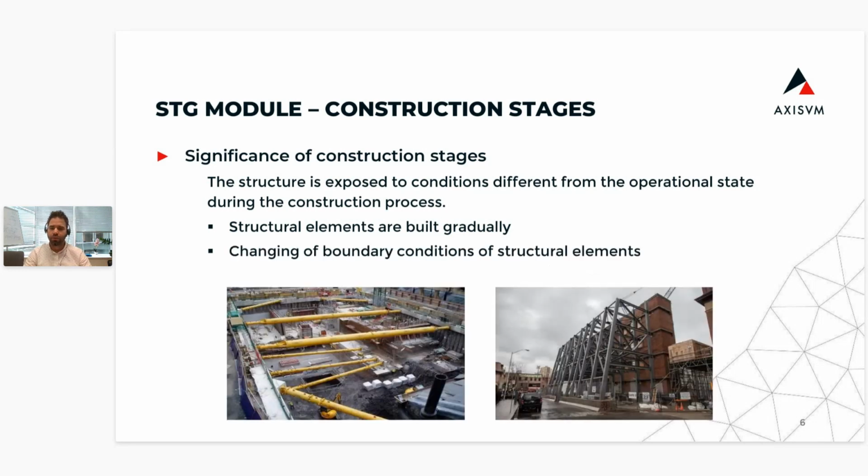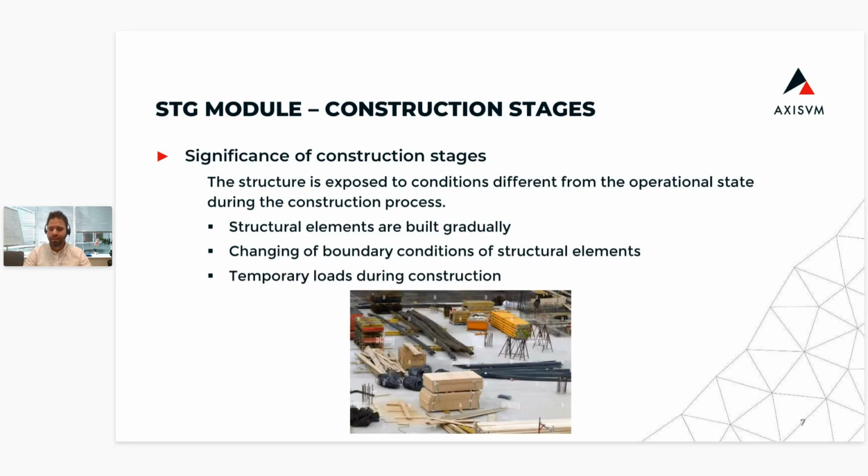Next thing is that during the construction process, the boundary conditions are often changing. So at one point of the construction process, certain supports can be present in the model and others are inactivated during the construction process itself. Another thing is the material loads. So temporary loads during the construction can appear and disappear, which can have a significant effect on internal forces and stresses, which should be taken into account in certain cases.